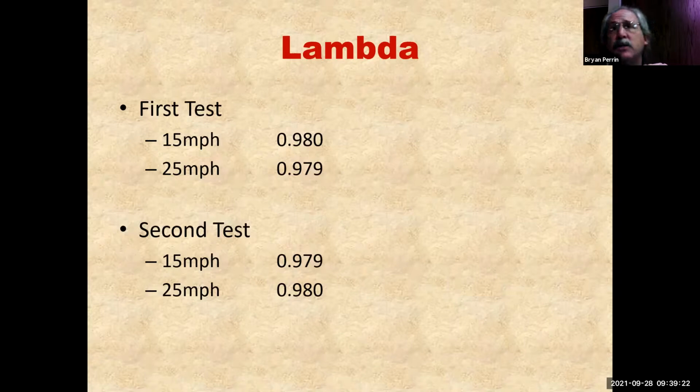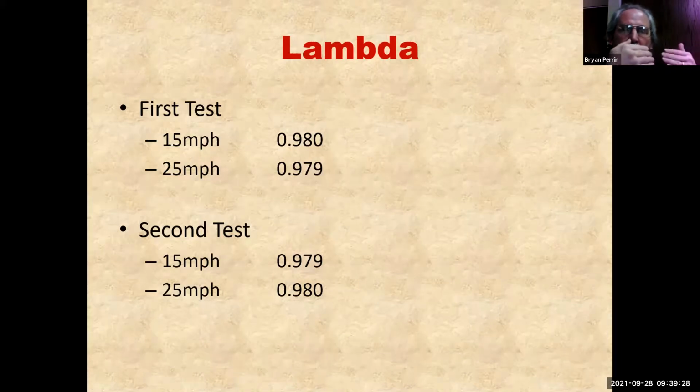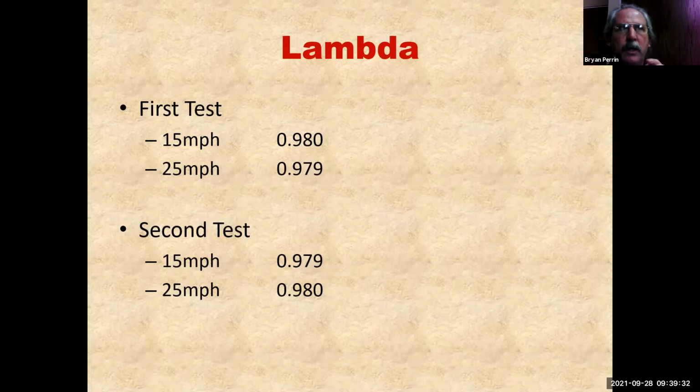which again makes sense because I have high CO. CO is a lack of oxygen, and lambda says we're running slightly rich. So again, can what lambda is telling me make sense with what I have? The other thing is we know my converter efficiency for oxidation, HC and CO, goes down the richer I get. So my hydrocarbon failure could simply be that I'm running too rich for my catalytic converter to oxidize my hydrocarbons. It may not be an engine problem at all.